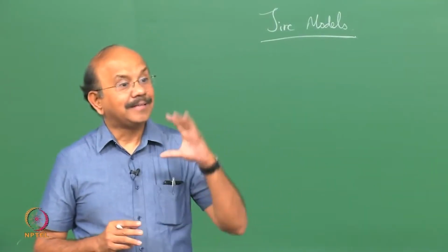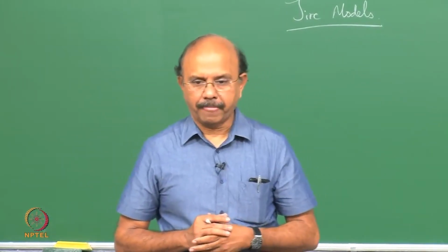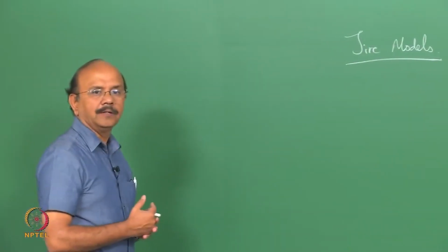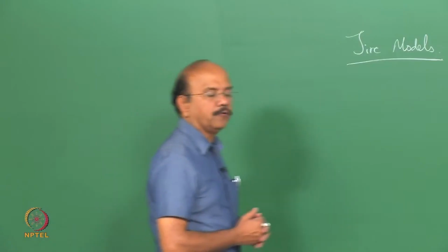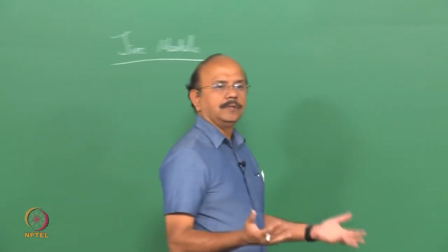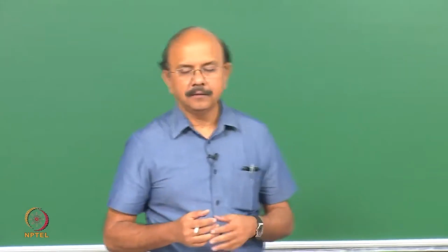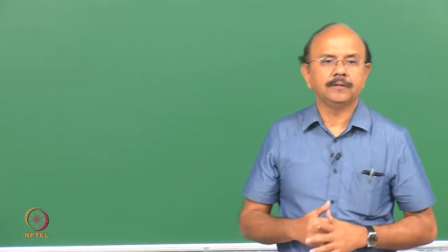In other words, that becomes an input into the software. So they have to give to the software how, for example, slip versus longitudinal force varies, how alpha to lateral force varies, and alpha and moment varies, and so on. Right? These graphs have to be input.